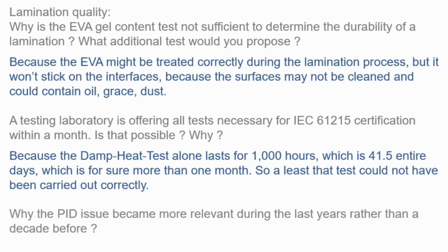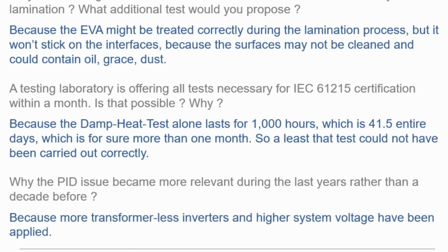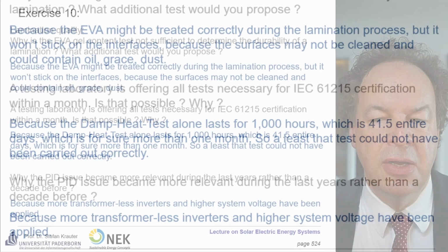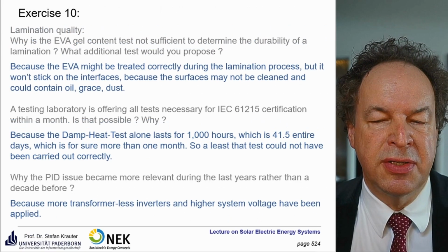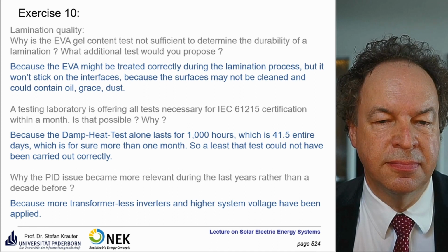Why did the PID issue become more relevant during the last years rather than a decade before? Because more transformerless inverters and higher system voltage have been applied. Also, some decades ago, the operators didn't pay such close attention to the actual yield.